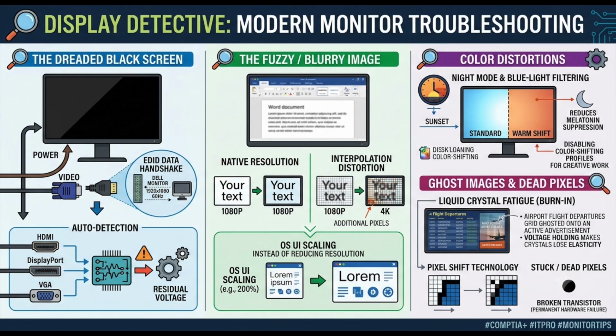That is the elegance of the design. It happens so slowly, and the shift is so microscopic that the human eye simply cannot perceive the movement. But at the physical level, it means a bright white line of a window border isn't resting on the exact same row of liquid crystals indefinitely. It spreads the load. Exactly. It distributes the voltage workload slightly to the neighboring pixels, giving the original row a fraction of a second to relax and preventing that permanent image sticking.